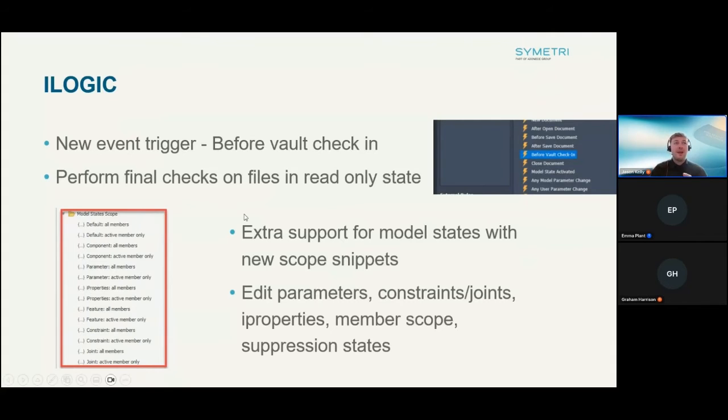So if you're wanting to add in a property when you open a file, you could create a rule that adds the property. Now, normally you would have to manually run that, but with event triggers, if you choose to run the rule after open document, you'll see it gives you that option to run that event trigger within there.